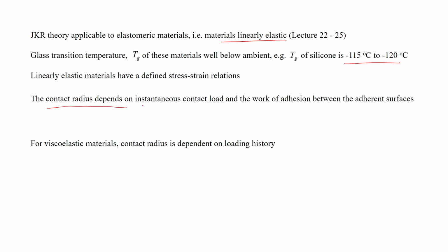Contact radius depends upon the instantaneous contact load and the work of adhesion between the adherent surfaces. There is a work of adhesion because of the surface energy or surface chemistry of the material. So, that is a thermodynamic quantity. But in addition to that, for an elastic material, whenever we bring two spheres in contact and apply some load over here, instantaneously some contact area is reached. It is not that the load was applied a few minutes back and the contact area is still increasing. It does not happen like that. That is for elastic materials.